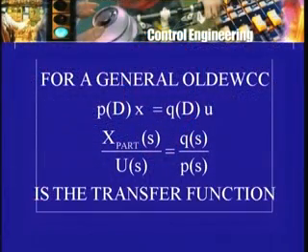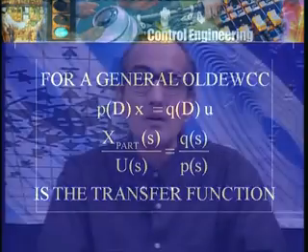Of course, if I don't have the programs, then I may have to do it myself, like I showed you for a second order differential equation how I might obtain the transfer function. And then of course, if I know u(t), I can find out U(s), etc. I can actually calculate X(s), get the inverse, and so on. So if no program or packages are available, no software is available, then of course you and I may have to do it all by ourselves.